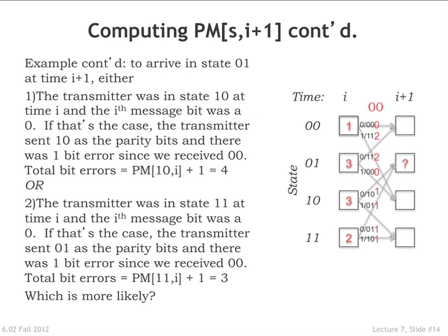So let's see, in this particular case, what would be the path metric value in this position? The same thing we did already, but just another chance to look at it. What would be the value of the path metric there? 3? Because you can either do 3 plus 1 on that arc for a cost of 4, or 2 plus 1 on this arc for a cost of 3. Okay, so it should be a 3 there, and this is the arc that you would pick.